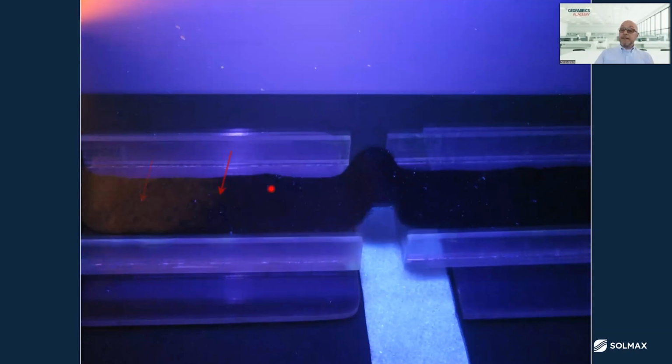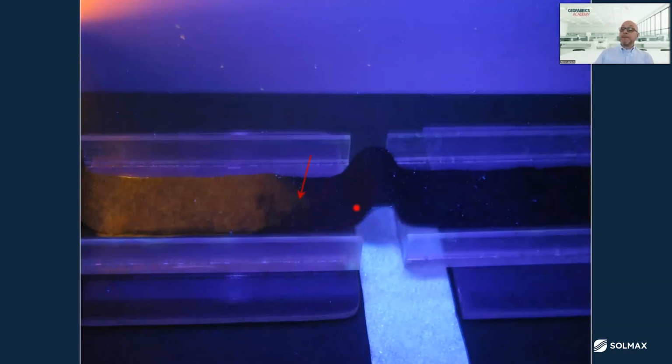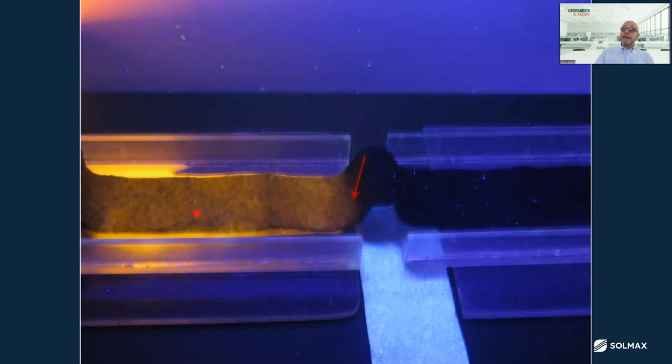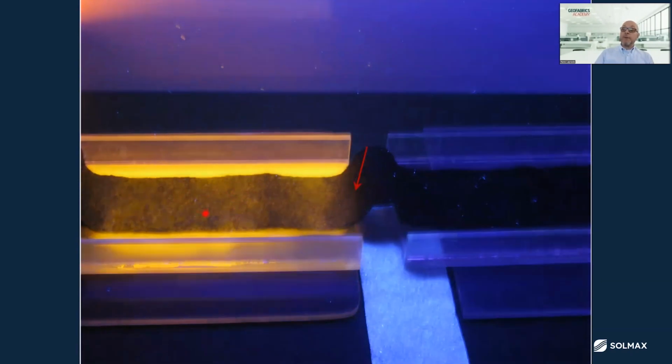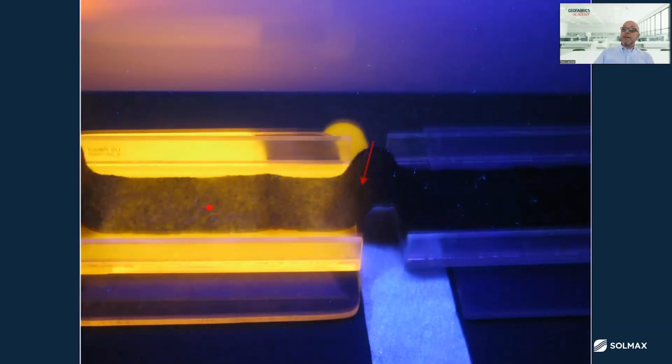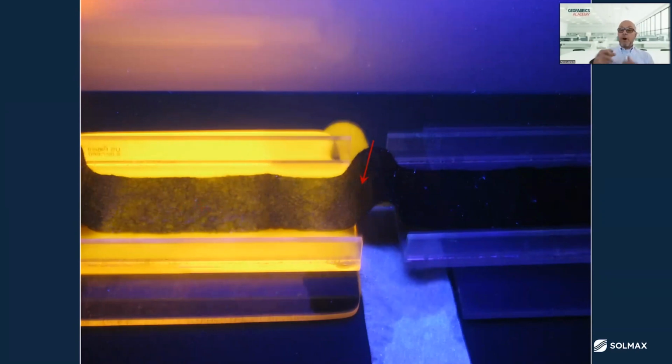If I do the very same test, this time with a non-woven geotextile, what you'll notice as this water progresses is a couple of things. You'll see that once it hits the speed bump, it stops. And on top of it, because this non-woven geotextile is made out of polypropylene, which is hydrophobic, it releases the water. Once all of the pores are full, the water is simply released back. So it does not have this ability to wick over any kind of significant distances. This is really drainage with the help of gravity.